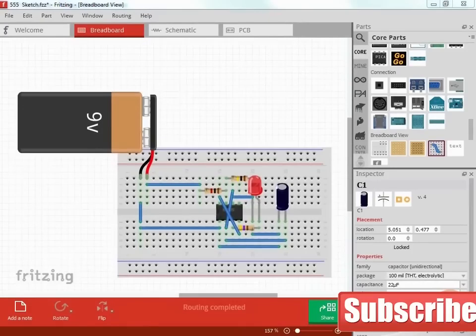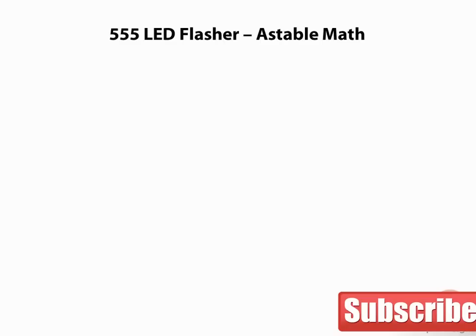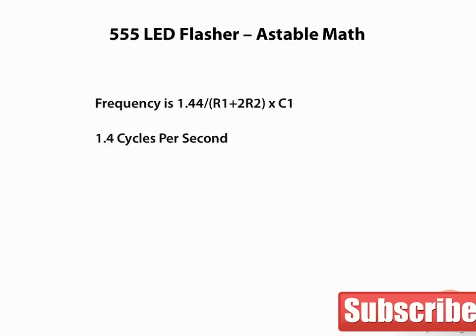There are lots of ways to make the connections. You'll get the hang of keeping things simple and neat with some practice. For our basic astable circuit, the frequency of the oscillations is given by the equation 1.44 divided by R1 plus 2R2 times C1. We chose these values for our circuit so that the frequency of the flashing is about 1.4 cycles per second.